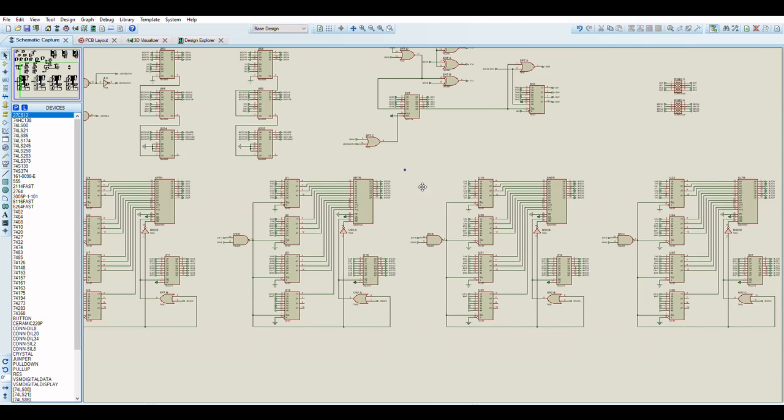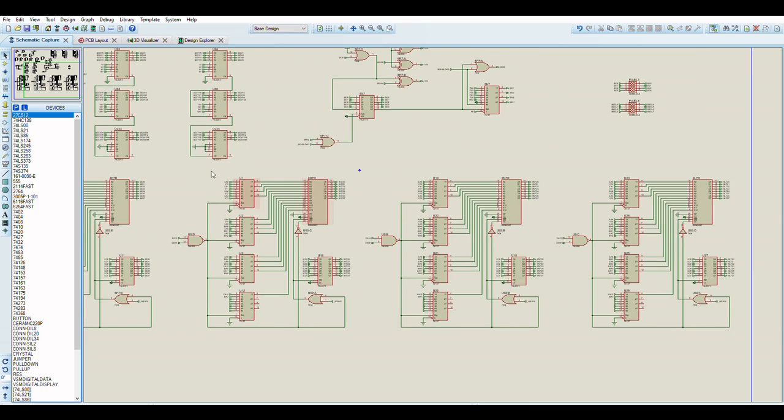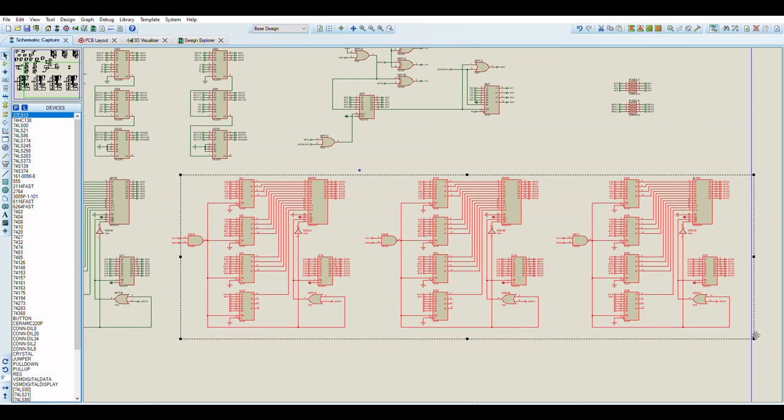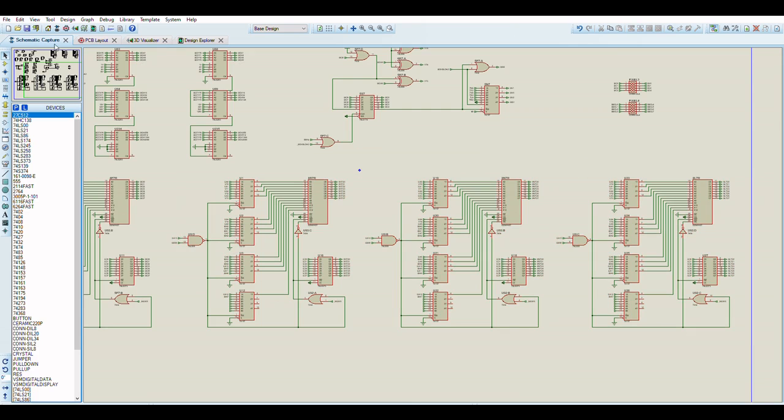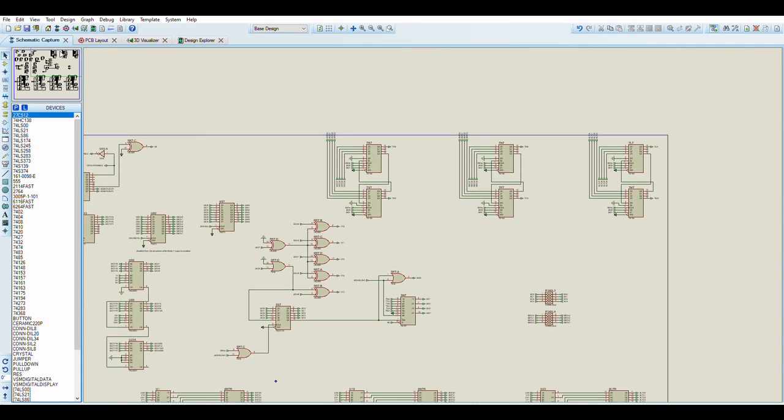These next 3 then look up from the current tile index. They look up into the tile pixel memory, and they go through the same kind of shifters as you would expect to see. The tiles, although they're 16 by 16, still work on the internal 8 by 8 pixel model.